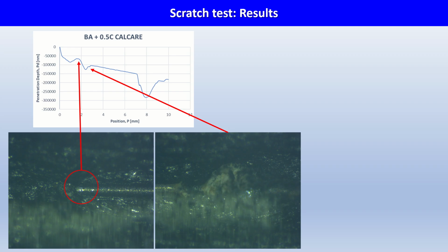The additive acts to lower the rheological moduli, the viscous and the elastic modulus. The scratch test shows that it is possible to understand which is the best surfactant for that, because the surfactant does not give any exfoliation process during the test, so no peak is observed in the profile curve.